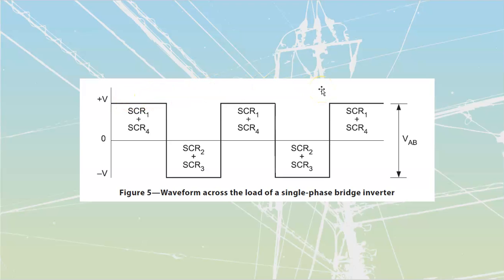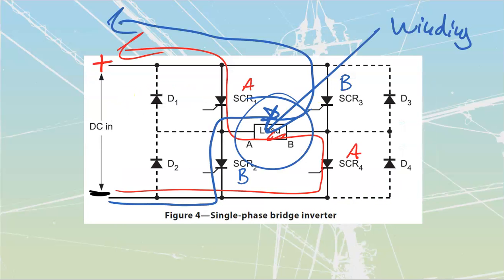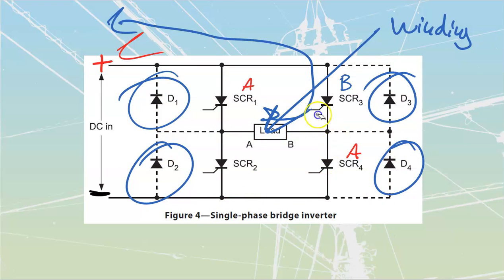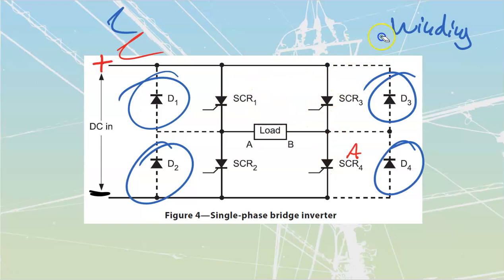There is also going to be need for some inductive protection, right? Because we know that anytime that we have coils, motor coils, they're inductors, and therefore they're going to want to collapse back in on themselves and create large induced values of voltages. And so we have to be careful that we don't allow that to take out a drive. As a result, we will place in these inductors over here, what we're seeing, diode 1, 2, 3, and 4, and those are just going to allow us to forward bias any sort of a collapsing magnetic field.